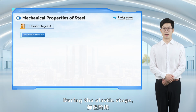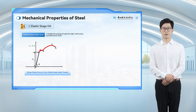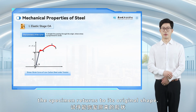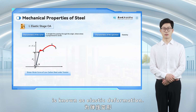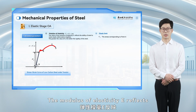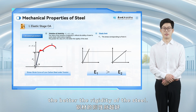During the elastic stage, stress is proportional to strain. The applied load in this stage is relatively small. When the external force is removed, the specimen returns to its original shape. This property is called elasticity, and the deformation in this stage is known as elastic deformation. The modulus of elasticity E reflects the ability of steel to resist elastic deformation. The greater the modulus of elasticity, the better the rigidity of the steel.